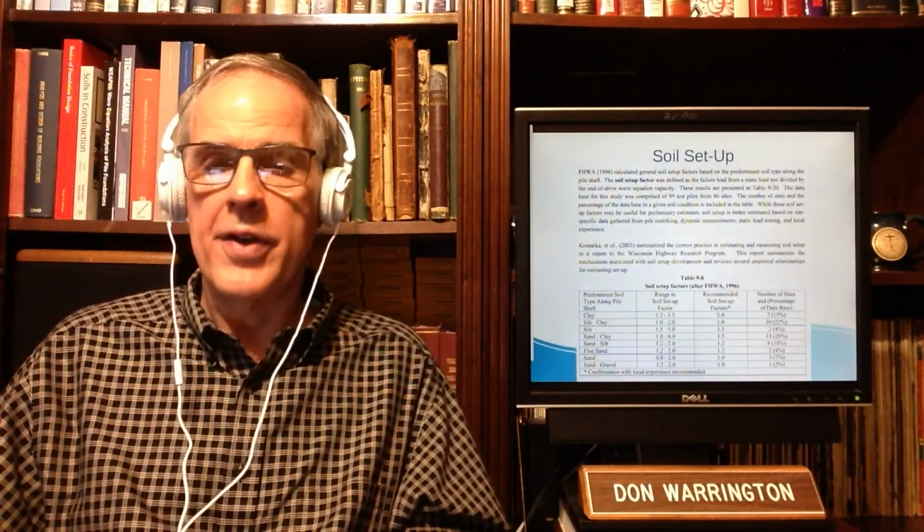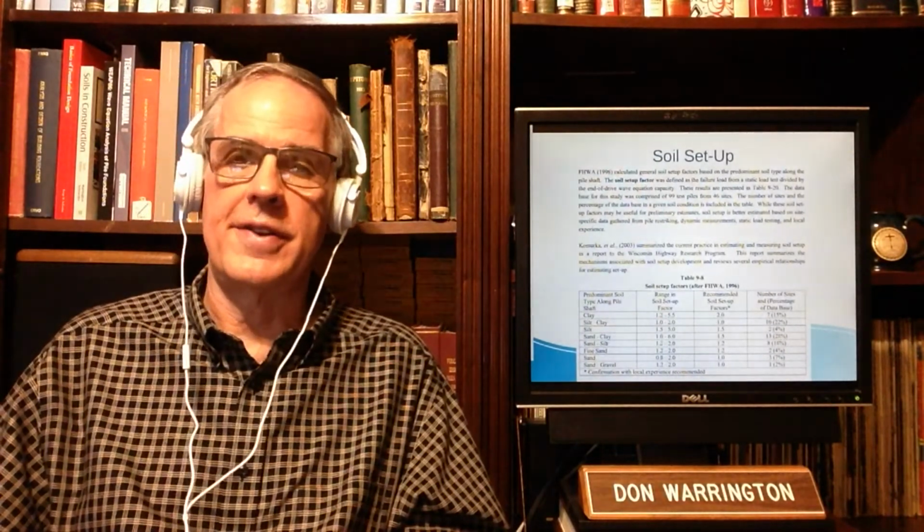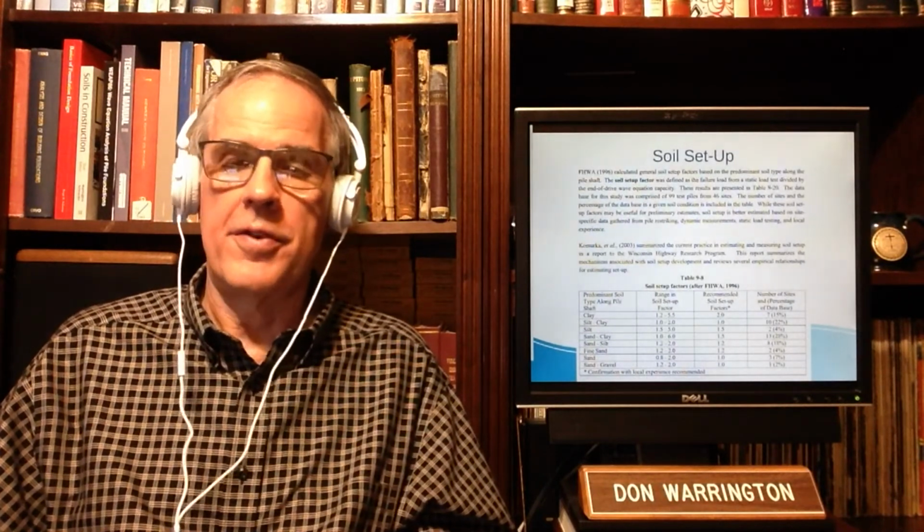Predicting setup is something of an art, although I said we've made a lot of advances over the years, and you see these setup factors given here. If you're given that, you can consult that table depending on the type of soil. In sands, in some cases, capacity actually goes down after it's been driven.